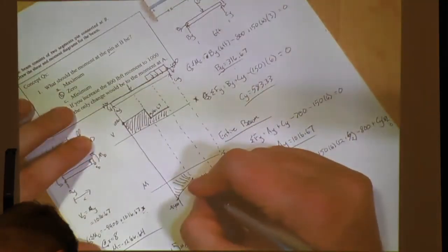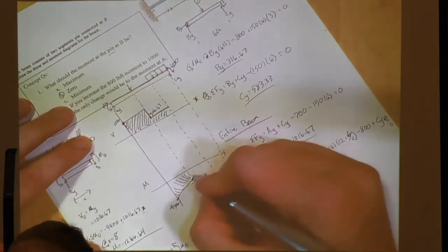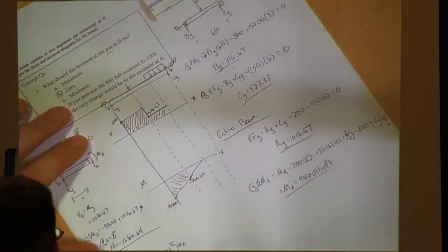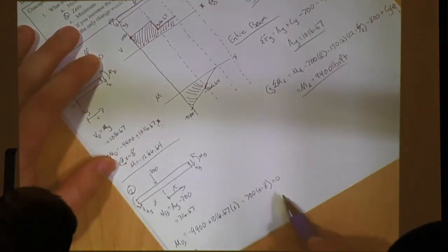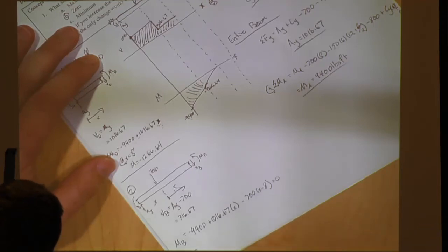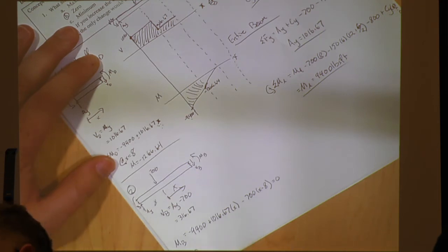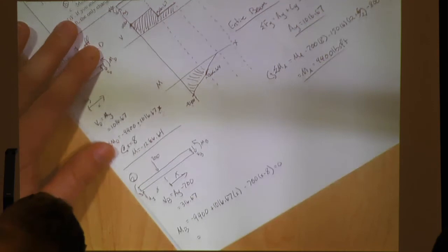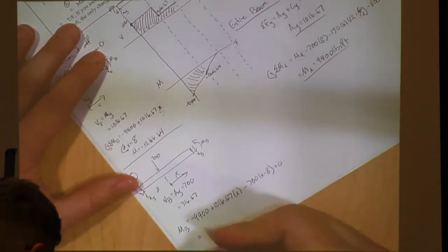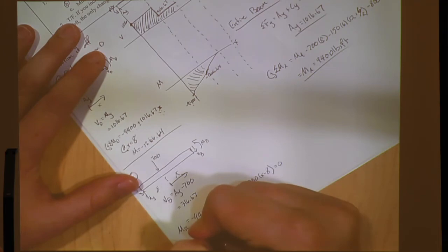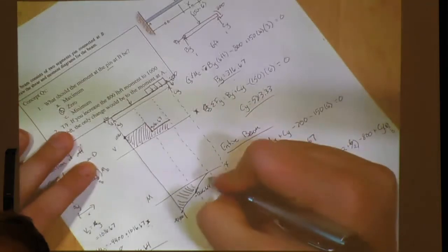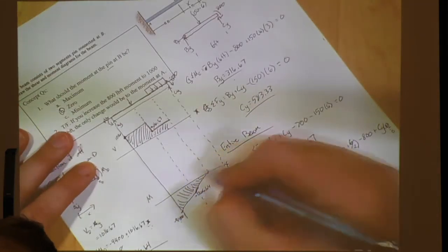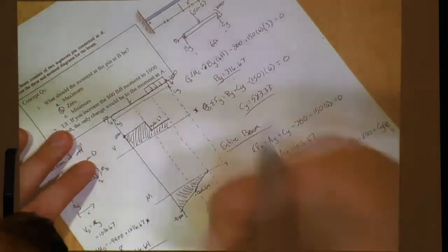So it's still going to be a little bit steeper, but it's going to come to 0 at point B. So when you multiply it by the total distance plus the 4, this equation will be 0 at B. Everybody understand that? Because there's no moment at B, because it's a pin. So at x equals 12, M equals 0. And that's why we got left with 0 here. And the slope does change, but I'm sorry, my angles aren't right.